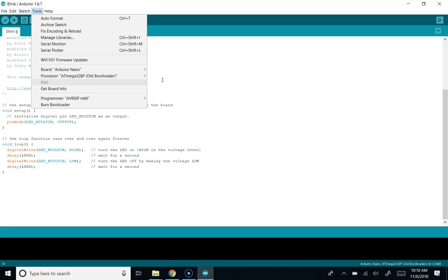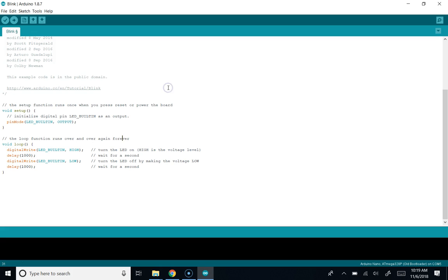If you try to send Arduino code to the mouse, how will it work? It won't, because your mouse is not designed to listen for Arduino code. It will literally just ignore the instructions. So what you want to do is, before you plug your Arduino in, check what's available in port. There might be a couple options there. And then plug in the Arduino. So I have no options in port. And now if I plug in the Arduino, I now all of a sudden have a COM5 port that I can write to.